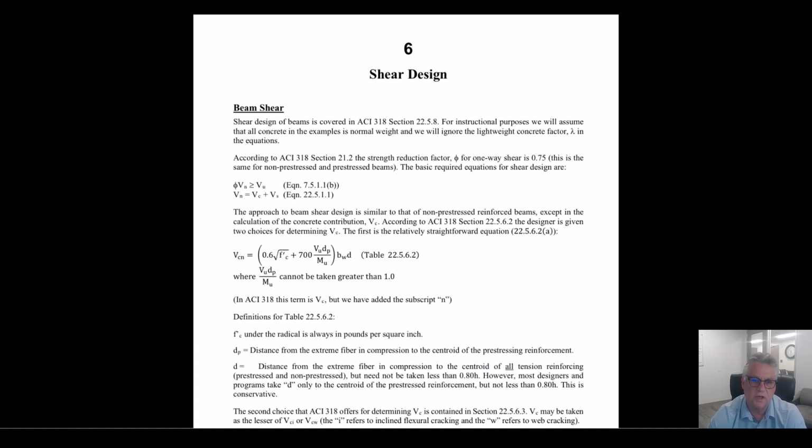And the post-tensioners came along. You know, and I'll back up. The pre-tensioners, and I really believe this, don't want you doing their work. So they want to make it as complicated as possible. They don't want it to be easily done by hand, so you have to own software that can do this. The post-tensioners, on the other hand, came along, and in my opinion, took a much more complicated type of system, an unbonded, undulating tendon running usually through multiple spans, and made a much simpler equation for FPS, somehow, some way.